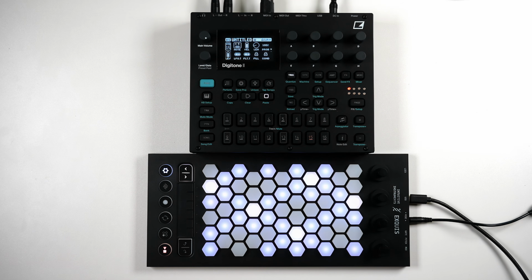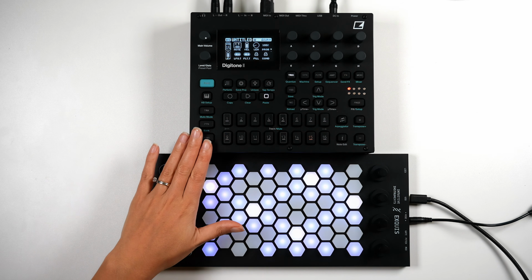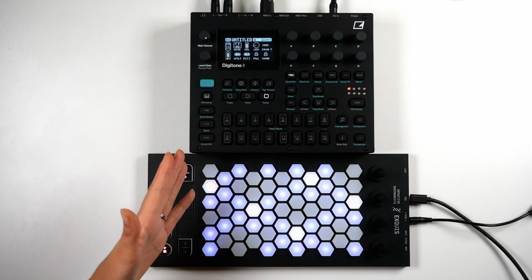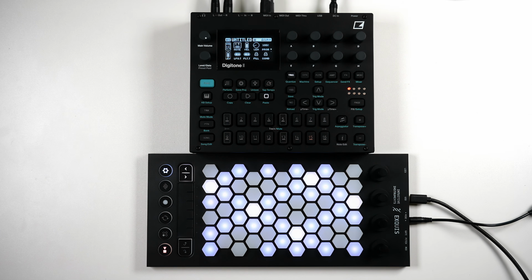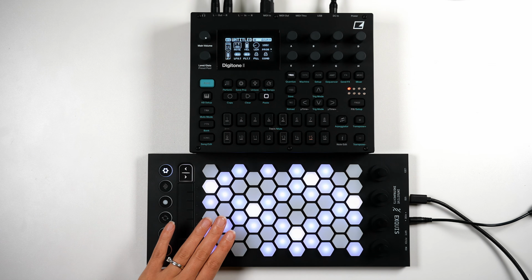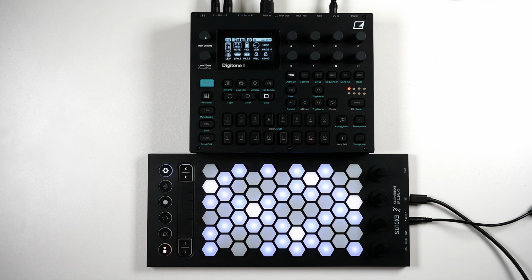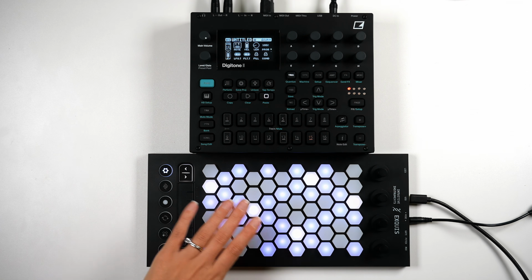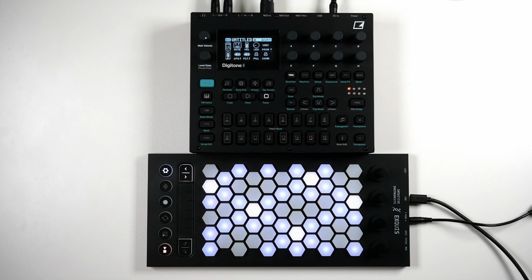Here's an interesting trick you can try with a multi-timbral sound module. Now, I've only personally tried this so far with the Digitone 2, so your mileage may vary a bit, but it's worth giving it a shot. If you remember our discussion earlier, the way that MPE works is by sending each note successively on a new MIDI channel. That's what enables us to get independent pitch bend, CCs, etc. sent to each individual note.